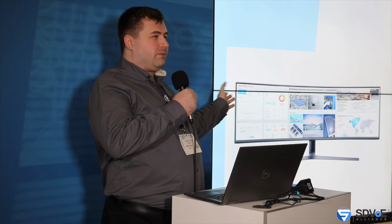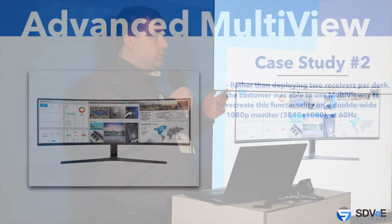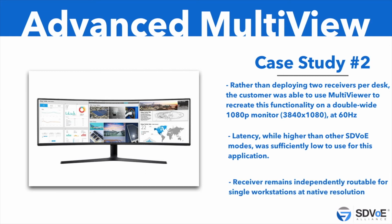And this actually gave them quite a bit of flexibility because they could also route that 3840 by 1080 monitor as a single monitor to any computer in the system. It gave them a lot of flexibility, and the multi-viewer was able to support any type of source sent to that second virtual monitor on the double-wide display. The latency is a little bit higher than the other modes of SDVoE, but it was still sufficiently low for the type of KVM usage that they were using. And again, the receiver was independently routable for a single workstation with a double wide, with native gen-locked support with the 100 microsecond latency that SDVoE is so famous for.